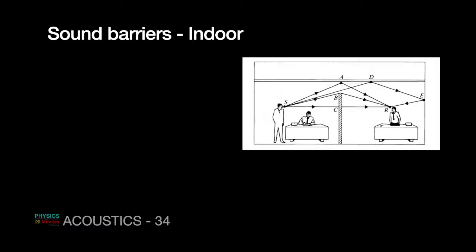Now diffraction. Suppose I exclude the other causes, let me go back to the previous one. Suppose this wall is very thick and heavy, then very little will be transmitted through the wall. And if you put some perforated coating, I will come to it later, then very little will be transmitted. And if you put a sound absorbing ceiling, then again reflection can be reduced. Under that scenario, diffraction remains the most dominant way by which the sound will be transmitted.